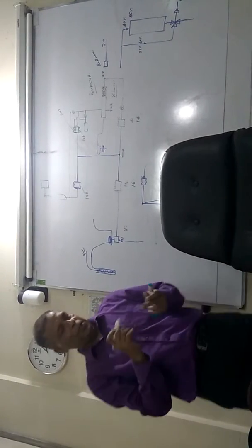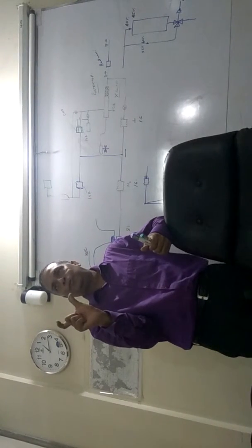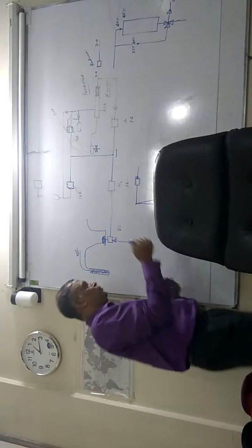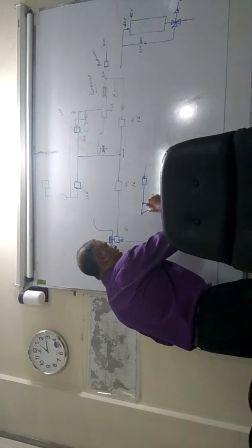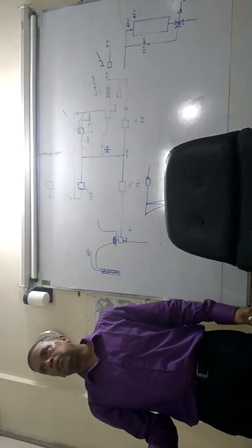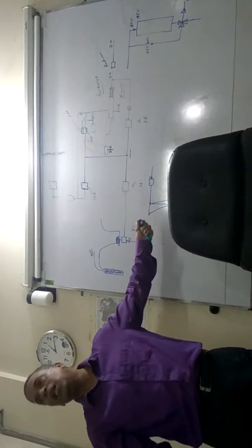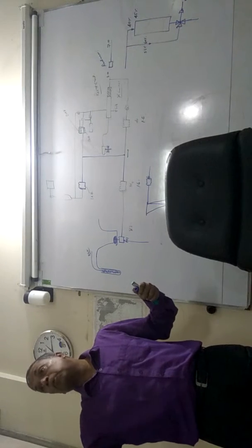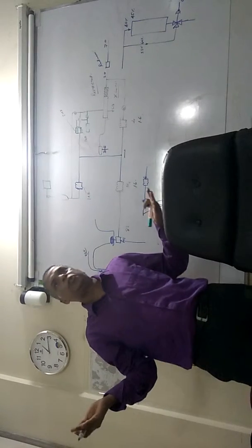Yes? Now, you must understand this. This is a proportional push. It is not equal to the earlier one. If it were equal, so if it moved this much here and also that much here, the resultant would have been like this. The distance between the flapper and nozzle would not have been the same. So this cannot happen like that. It cannot be equal movement of the flapper's top due to the proportional action bellow. It may be in proportion.